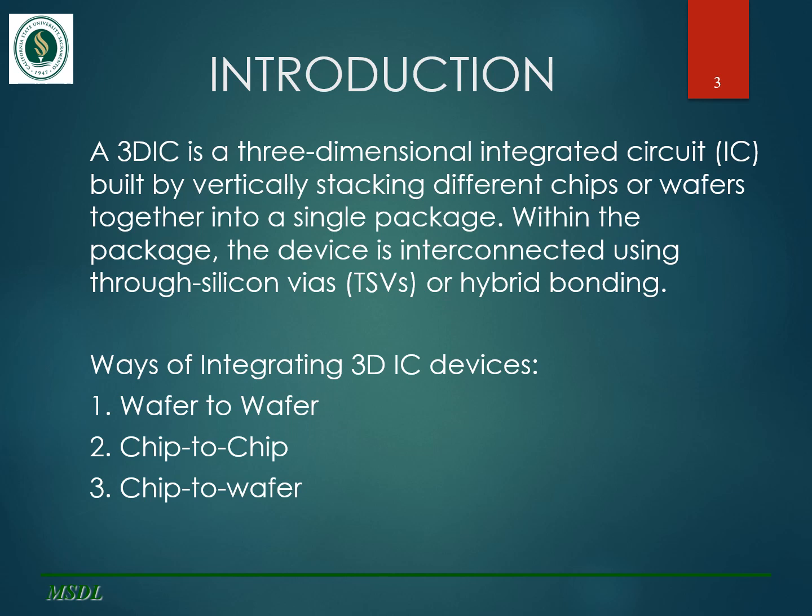For most of that half century, the scaling was relatively easy and was associated with about 30% reduction of transistor cost, greatly improved performance and markedly reduced power consumption. However, recently the trend has changed dramatically and it is now harder, technically and economically, to achieve dimensional scaling. As a result, there are diminishing improvements in transistor cost, power or performance, and a new form of scaling is shaping up as an alternative to maintain the exponential increase in integration. This new form of scaling up is 3D integrated circuits.